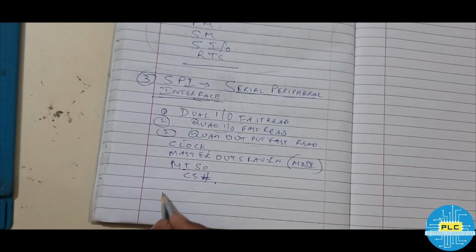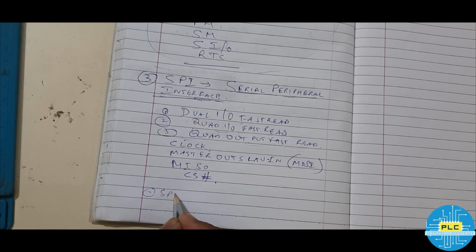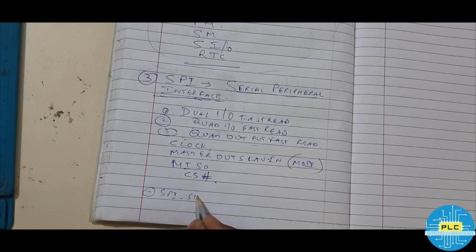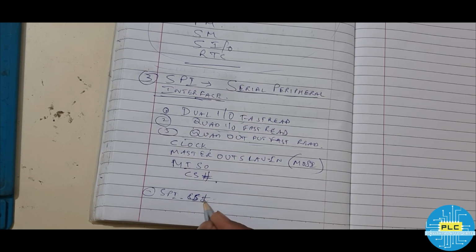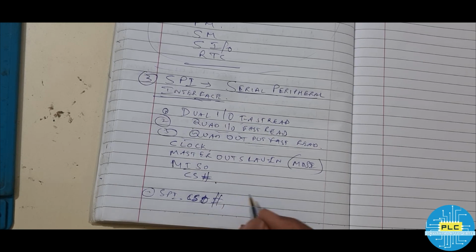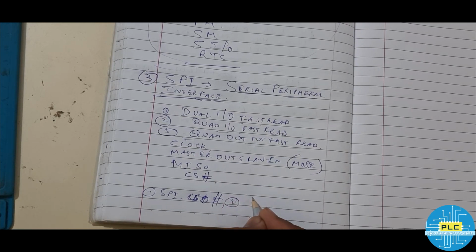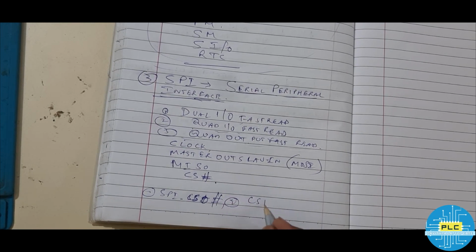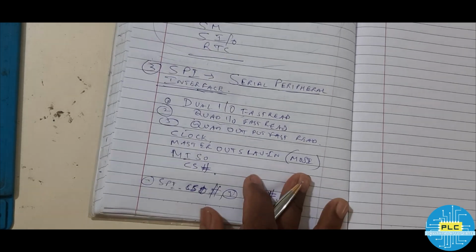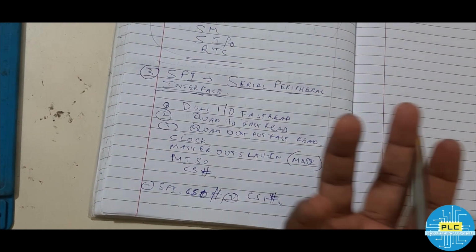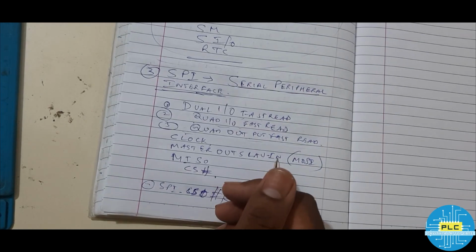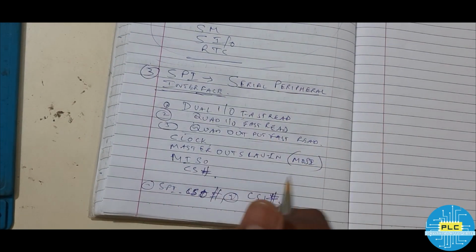One is SPI chip select CS0#, and the second one is CS1#. These two are used to access separate SPI flash components in descriptor mode.